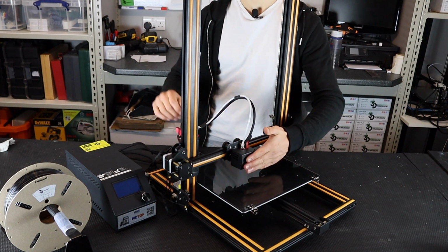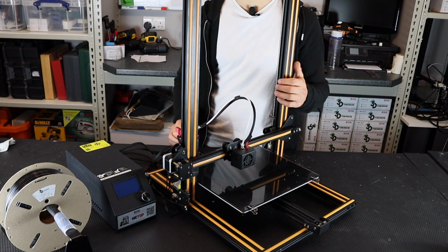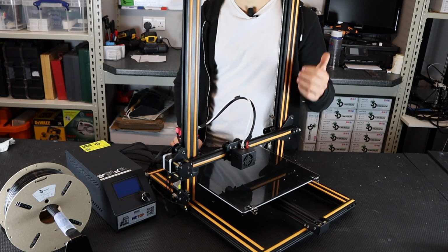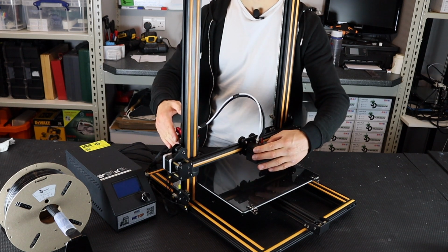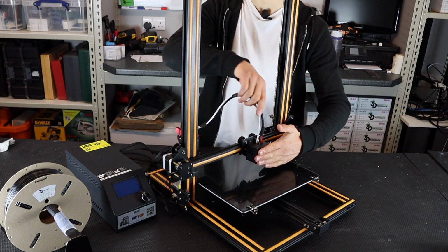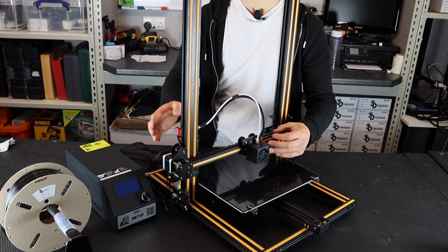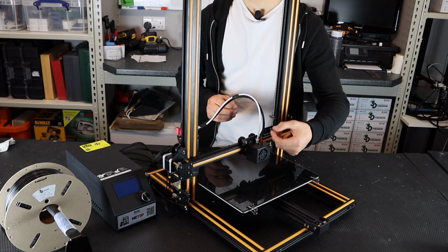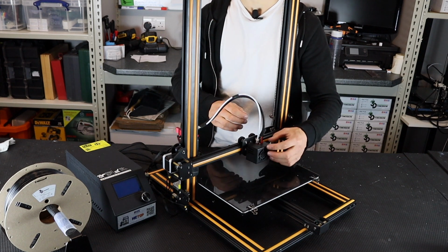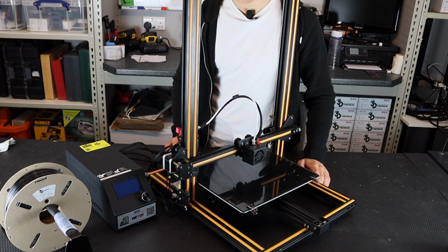So we have the hot end and the drive gear, and then everything in between, and this encompasses the extrusion system. You might hear of two extrusion systems. We have Bowden, which is what is featured here, where the drive gear is separated from the hot end by a Bowden tube. You also have direct drive gears, which is where the drive gear will be situated directly onto the hot end, and there'll be a minimal gap between them, and so it pushes straight in. There are pros and cons between these two systems, and I can go into this in the comments if anybody would like me to discuss this.